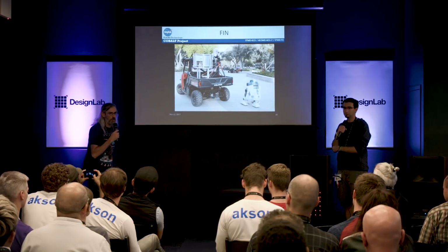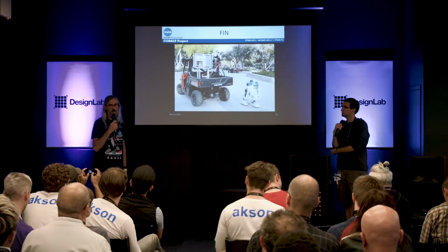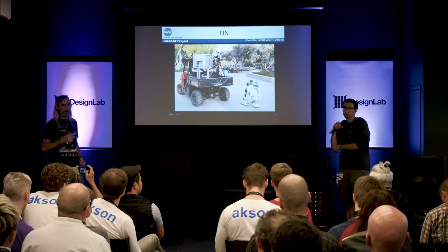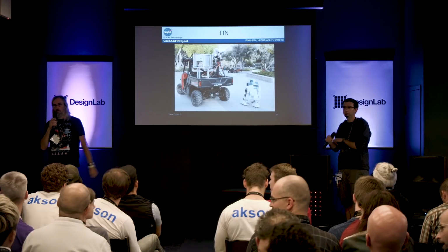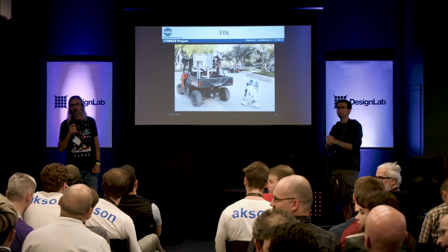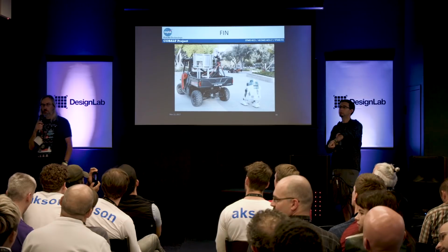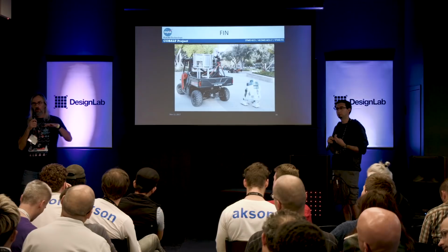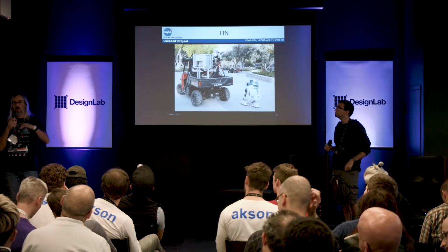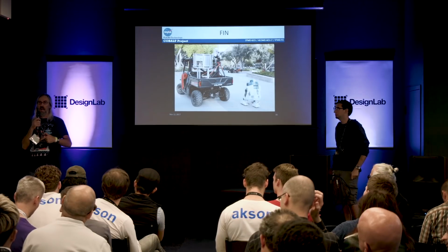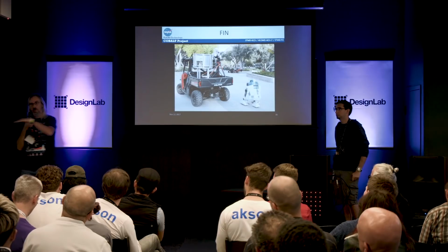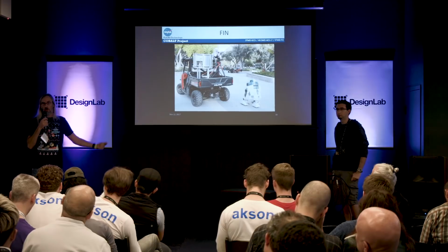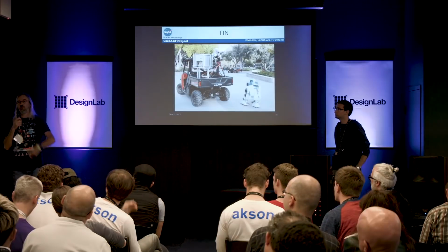So, Sam, we have a couple minutes for questions, and then we'll answer more out there. Anybody? Yeah. Were you using the LiDAR for mapping or just ranging? It was basically ranging, but also probably more important for measuring the velocity. Since it's a Doppler LiDAR, it can directly measure the 3-axis velocity of the vehicle, which you can use to update the inertial navigation.